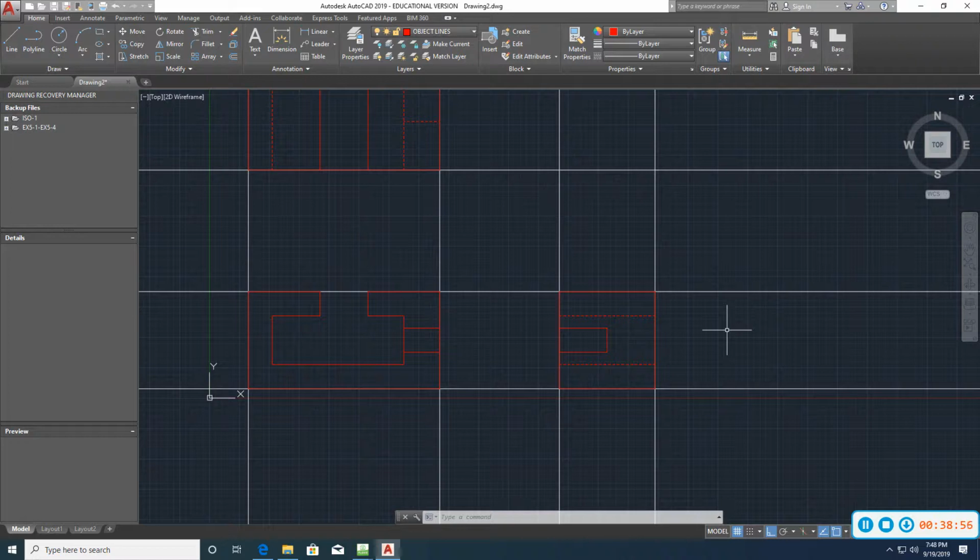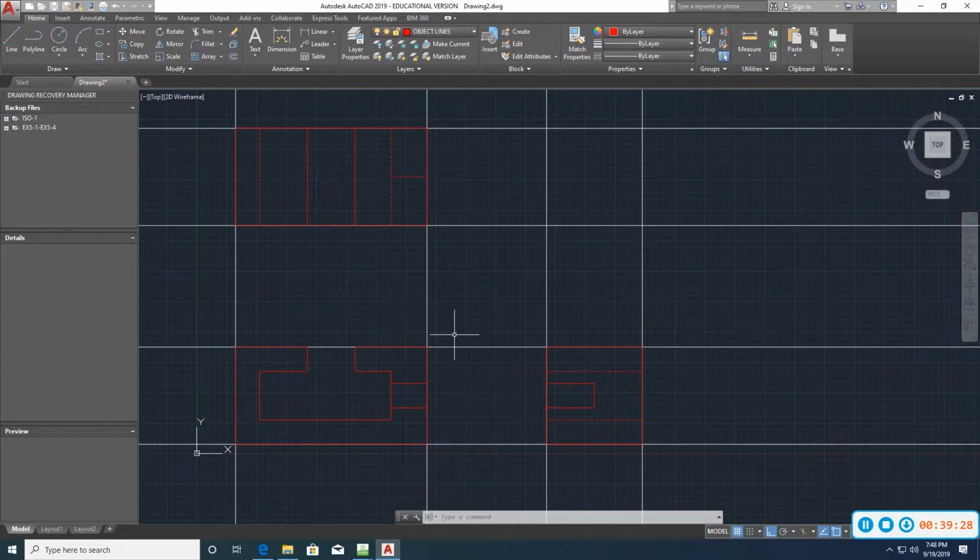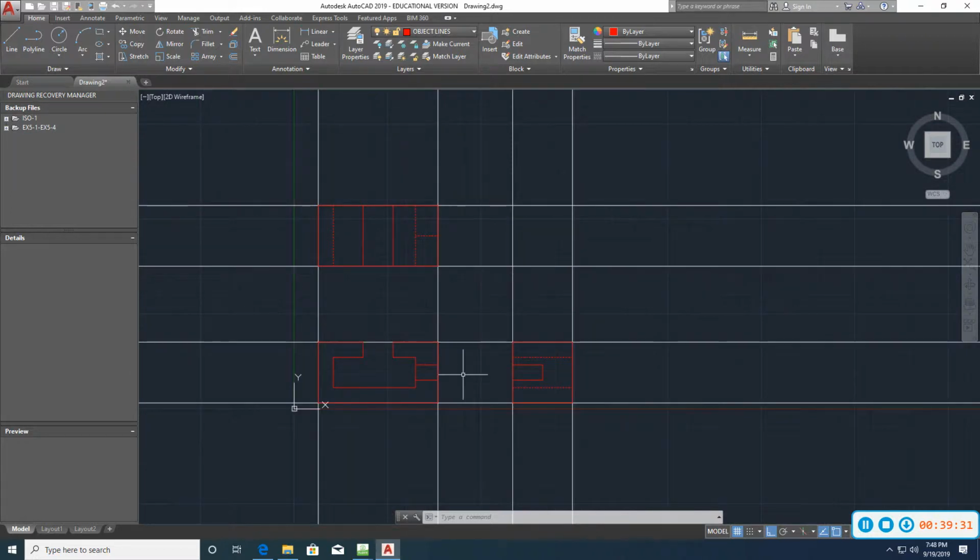Did we get it, Cassandra? What do you think? Have we missed anything? If you're looking from the right side, we can't see that corner right there, so that's hidden. But we can see this notch, right? We do see this notch, and we see the other side of the other wall here, so that's what this line is here. We can't trim that because you do see that other edge. And then I think that's it, as far as the geometry goes.